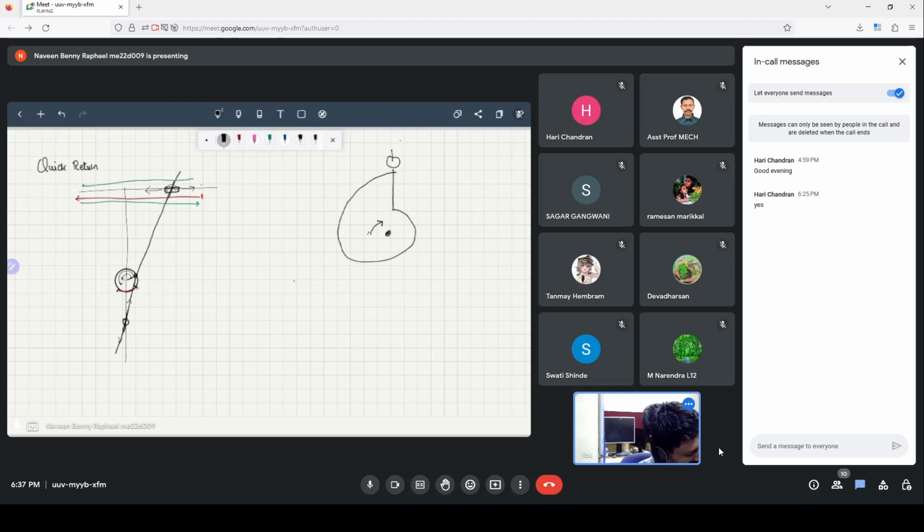if you think for a while, it becomes clear that the linear motion will be kind of like a step, because over here you'll suddenly jump to the bottom and then the cam will continue rotating towards the left and so on, and eventually once you reach the top, it will again fall down. So that will be how the cam output will look for this.